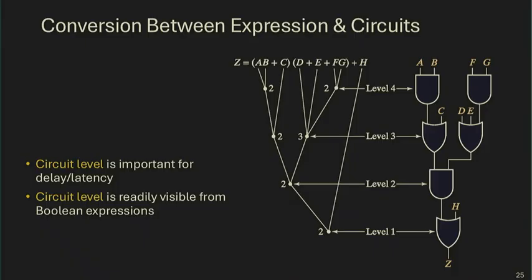In our 2-level circuits, we have only 2 levels of gates. And that is the best method while still being able to implement any circuit. Remember, sum of minterms and product of maxterms are canonical forms, and you can implement any circuit using SOP or POS. But you can also sometimes go to more levels, 3-level, 4-level, 5 levels, to get fewer gates and hope for them to also consume less power. And that is a trade-off we can make by manipulating the Boolean expressions.